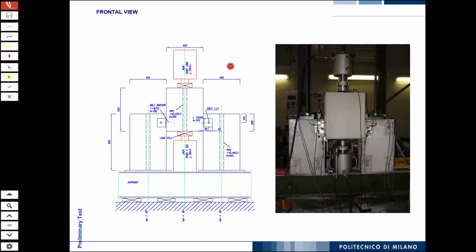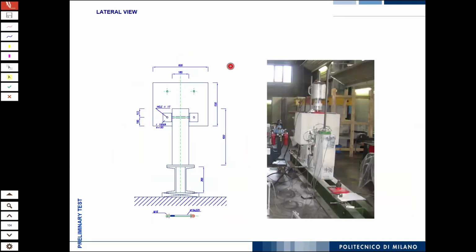Actually, you can appreciate here the creativity of engineers when they have to make a test in the lab. You see that this block here was made with 1, 2, 3, 4 steel embedded plates, because when we damaged this part, we tilted it and we could use the other. So we could use the same blocks actually to make 4 tests. Because casting these elements is not a big cost, but it's a big work. And so you want to reuse them as much as possible.